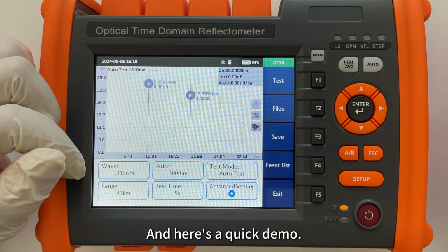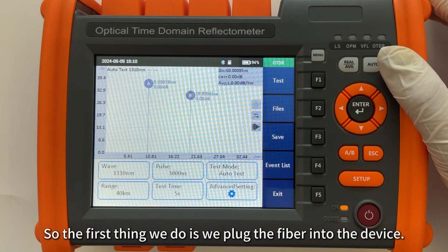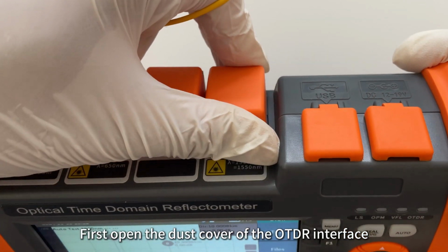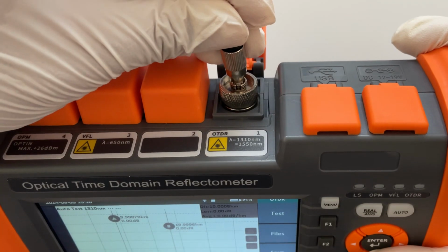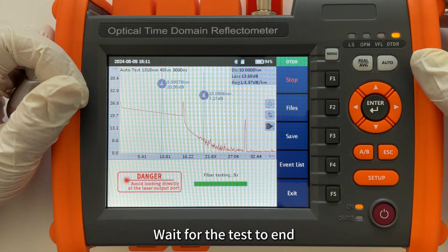And here's a quick demo. The first thing we do is plug the fiber into the device. First open the dust cover of the OTDR interface and connect the fiber optic. Here we can choose the automatic mode to start the test. Wait for the test to end.